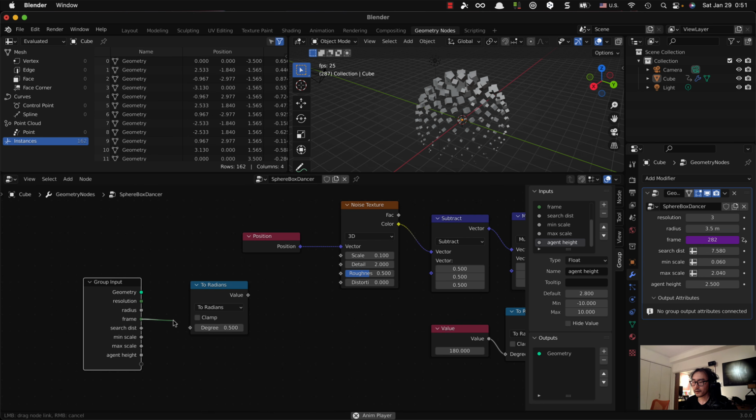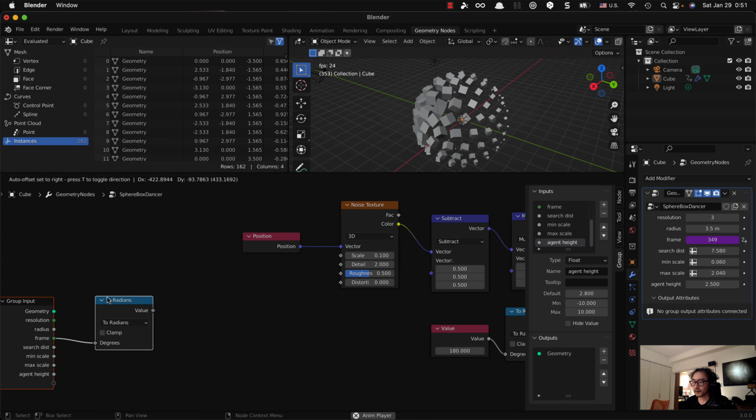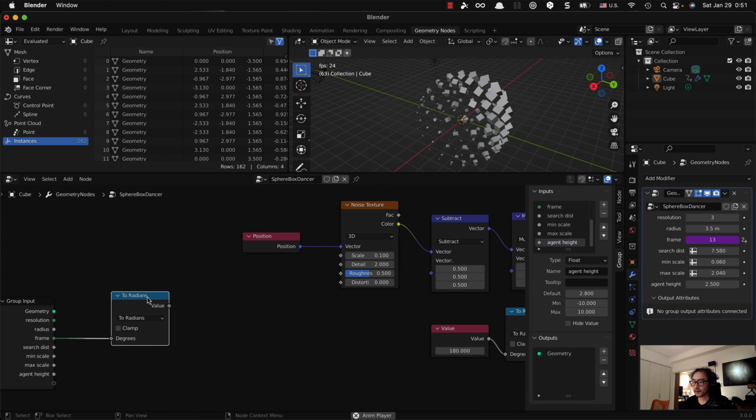Okay, like this. Now, the important thing here is that we do want to create the loop animation. So even though we want to create the rotation animation from the first frame to the end frame, we do need to link from the end frame back to the first frame, continuously going back to the same rotation value. So that's the key concept here in order to create the loop animation.